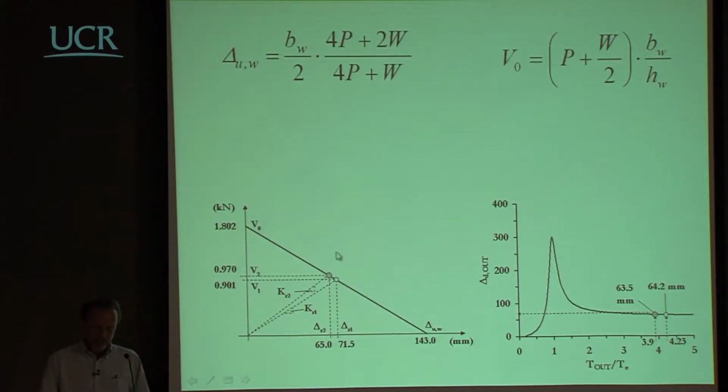You guess a displacement here. You compute a period of vibration. You compute this spectrum here. You enter here with the ratio of the period of vibration that you have calculated, and you read the displacement here. If this displacement is the same or close to what you have been assuming here, then it means that your structure will actually behave like that.